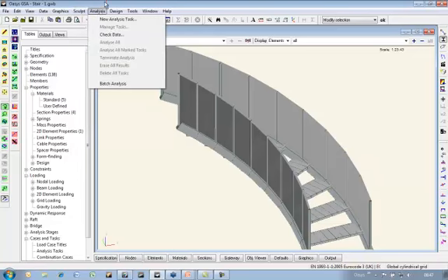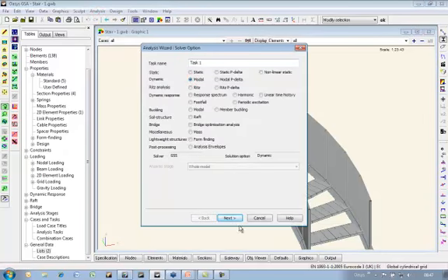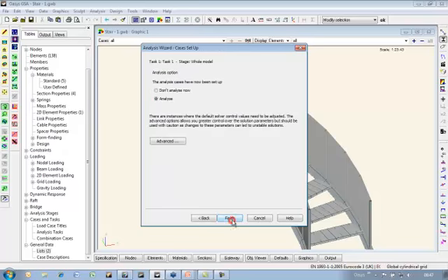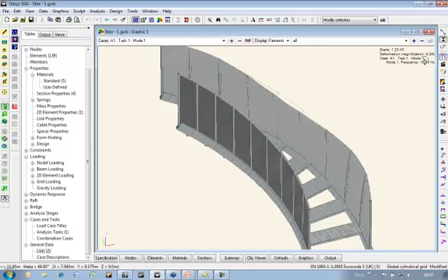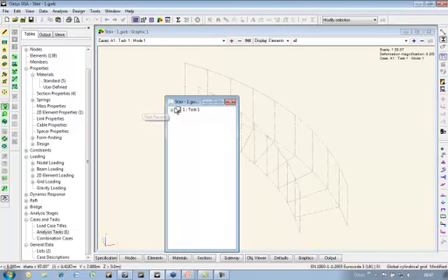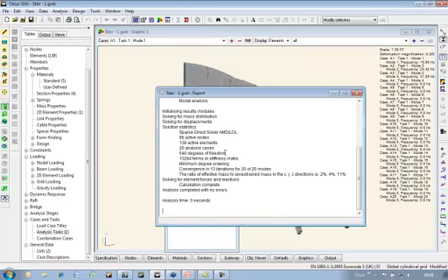So let me do a new analysis on this. Let me just check the modal. No additional loads. And this is high frequency, that's 17 Hertz. So let's delete the results, analyze that, and ask for, I don't know, 20 modes, but with upper frequency 17, let's go up to 35. Make sure we get, as it happens, only the first 3 modes are suitable.